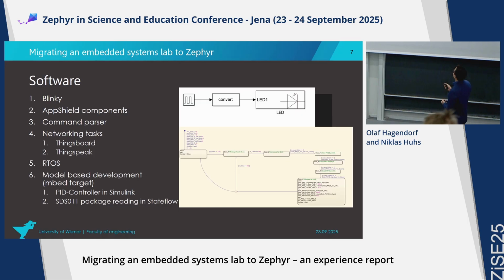And on the bottom, you can see Stateflow, which is a tool for state machines within Simulink, kind of like a subsystem with a different language, where we used Stateflow to read out the packages that are coming from the SDS 011 particle sensor, going step by step, and in the end, calculating the real values of the different particles that are detected.